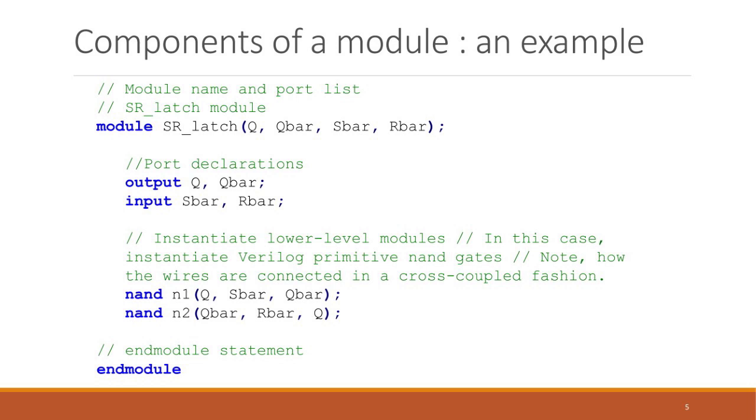Here in module instantiation, what we are doing is creating an instance from a module and placing it in the circuit while connecting proper signals to it, of course. Since you have only been familiar with software programming languages so far, you might feel like this is similar to function calling that you have seen in those languages.